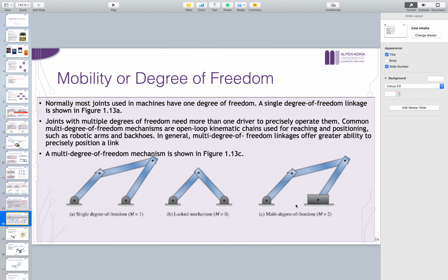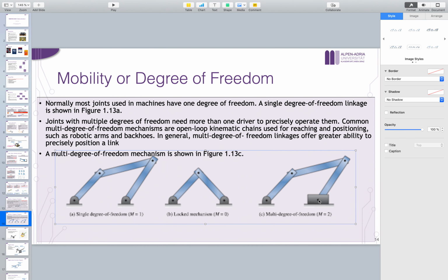It can only be either along this or going up, lifted up or lifted down. So what I mean here is that this third joint doesn't rotate, so it has 0 degrees of freedom, but this joint that is connecting these two surfaces has 2 degrees of freedom, which is sliding here or sliding up and down.